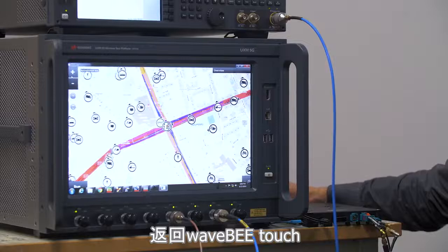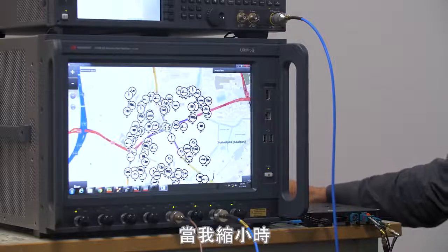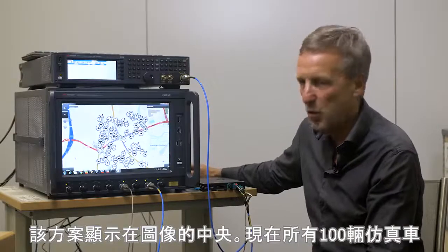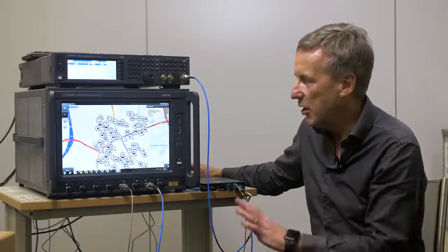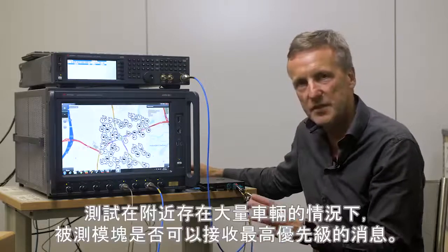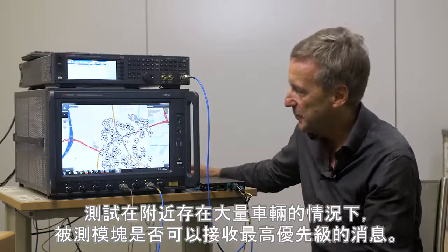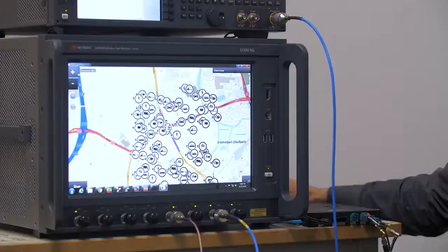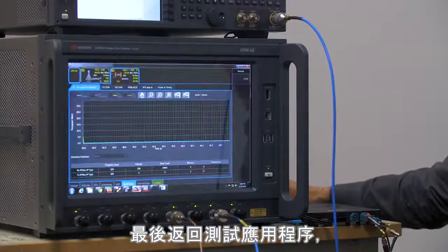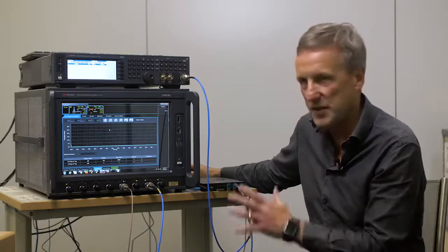If I go back to my WaveB Touch and I expand out, we can see here's the scenario in the center of our image, but we're seeing we have 100 simulated vehicles all transmitting over the PC5 link. So the test would be, does my module under test still receive the highest priority messages in the presence of all these other vehicles? Finally, let me go back to my test application, and I'm going to look at the BLER throughput from our transmissions.